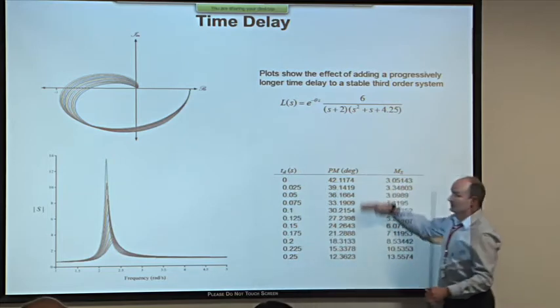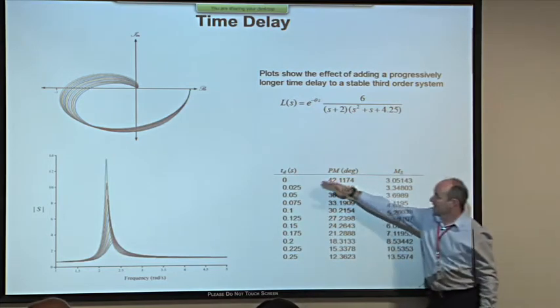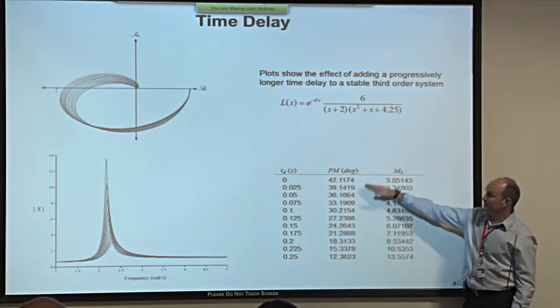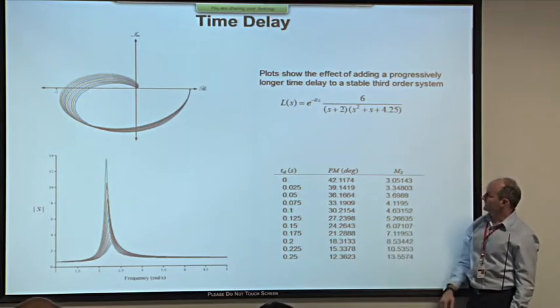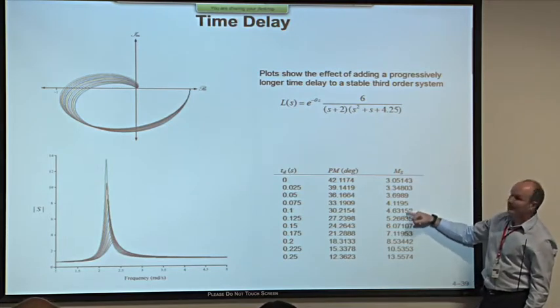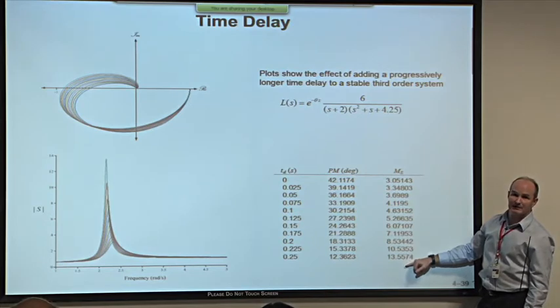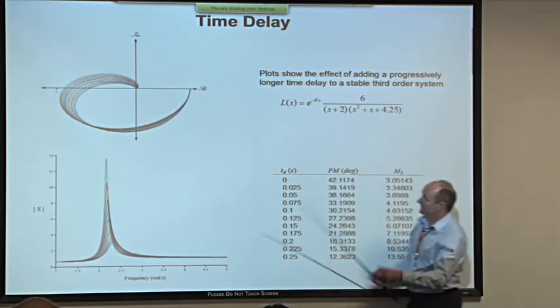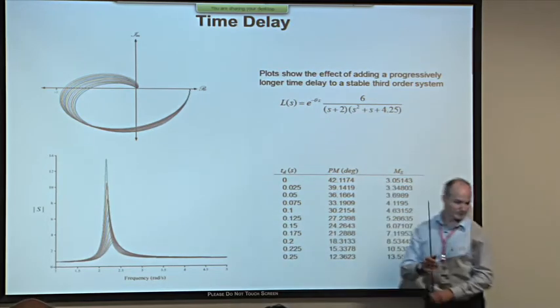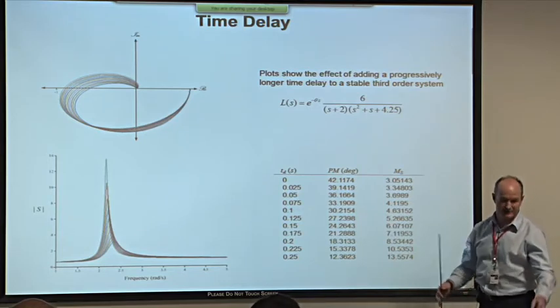So what I've got here is visual confirmation that time delay is eroding phase margin because there's frequency-dependent phase lag involved, and we're getting some very big numbers in the MS. There's a sensitivity magnitude up here. I'm just saying take it seriously, that's all I'm saying.